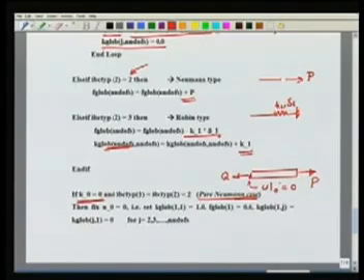Now generally we are interested in the strains and the stresses and maybe the relative displacement of 2 points. So why can't we fix this constant to an arbitrary value? So what do we do? We fix essentially maybe this endpoint to a value 0. So u at 0, we fix it at 0, and we find a solution. We see that this solution is not going to give you any different state of stress and strain.